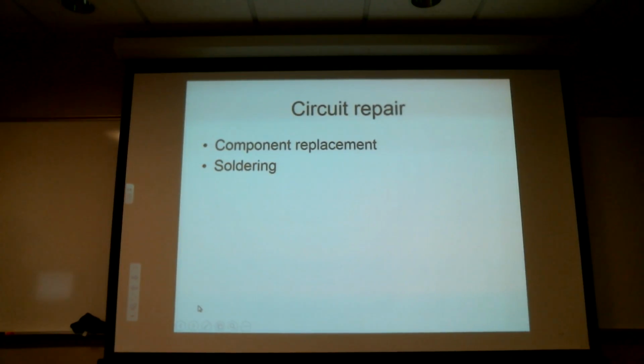You should be able to derive some common problems that can occur in a few normal common circuits. So what could go wrong in a charging circuit? What could go wrong in a typical lighting circuit? Just be able to describe a few things that can happen there. You should definitely have in your mind how a DC generator is wired and how an AC generator is wired. Remember, we had delta wound, Y wound, and in the DC world we had shunt or parallel and series type arrangements. So you should have those in mind. You better be able to make use of the volt drop check.